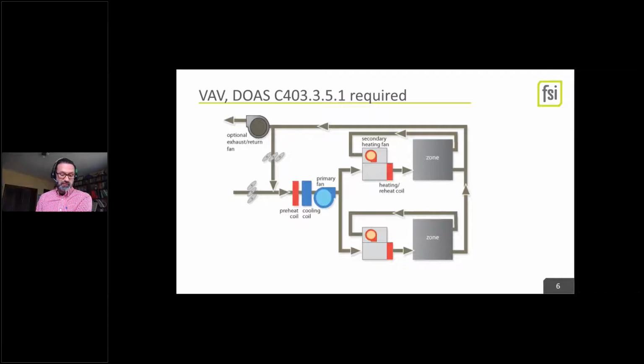And then replacing that rooftop equipment with a DOAS unit with ERV or HRV, heat recovery or energy recovery ventilators with the appropriate effectiveness. The nice thing is that your ducts will be oversized. Your main trunk down an existing building would be oversized in that VAV unit. It would have been sized to do all of the conditioning with air. And your new DOAS unit will only need a small portion of that duct. You can either reclaim it or you can just have a really low pressure drop duct.